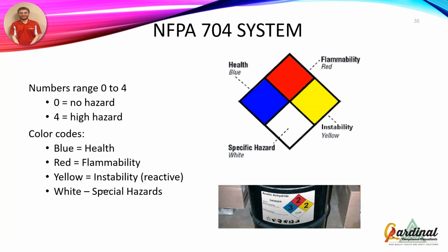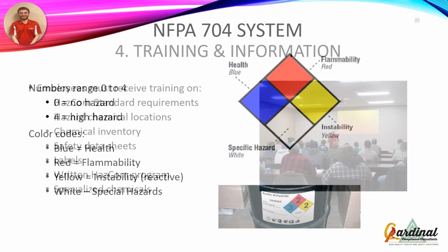So anyway, go ahead. Yeah, so that's a good point too. I remember mentioning that earlier, but yeah, a lot of those safety data sheets now have this NFPA rating. A lot of times it's either on the first page or the last page, and it's super easy to use. It tells you exactly what you need to put on those secondary containers as need be. So just like Rich said, though, make sure you're looking out because it can get confusing with that Section 2 and it being basically the opposite of what the NFPA or the HMIS are. So just be careful of that.